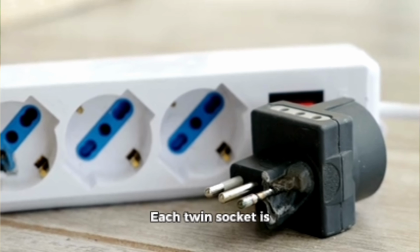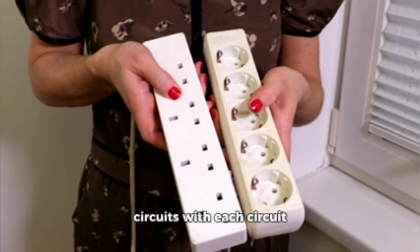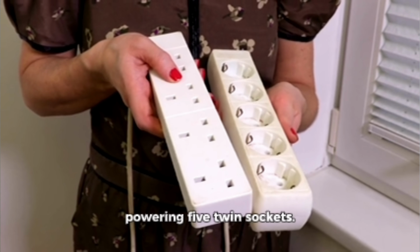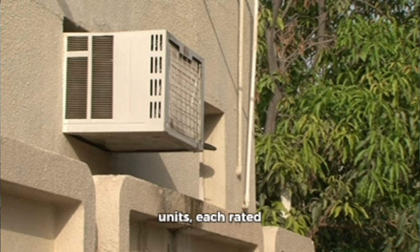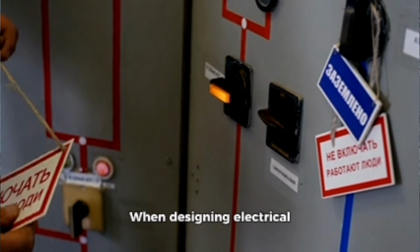Each twin socket is rated for 400 watts. We'll divide these into 20 circuits, with each circuit powering 5 twin sockets. We have 6 AC units, each rated at 2000 watts. Each unit will have its own dedicated circuit using a 32 amps MCB for protection.